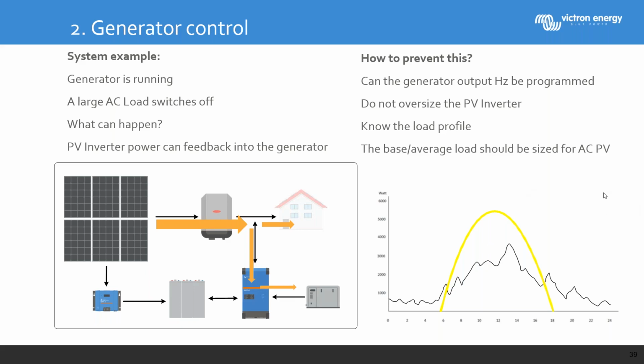So obviously, do not oversize the PV inverter. Have a really good understanding of your load profile. If you have a big load that can switch on and off, you have to be informed of that, and you have to take it into account.